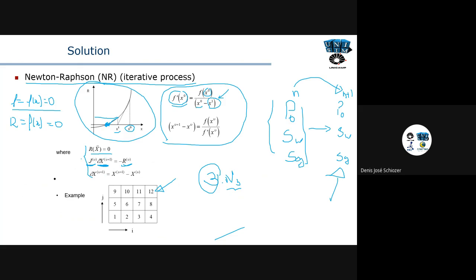So when we solve an iterative procedure in a reservoir simulation block, we are solving for this, okay? This is the most important concept we have inside the reservoir simulation blocks. So we are trying to solve this. And I'm going to go the number of iterations that I need in order to converge all the pressures and all the saturations to the values at the end of the time step, okay?